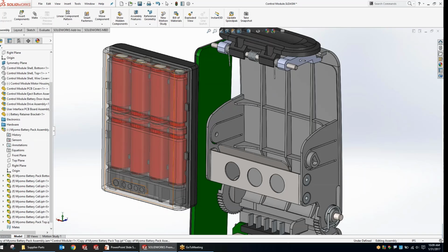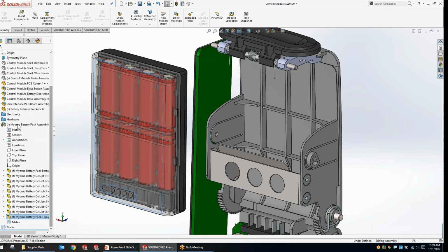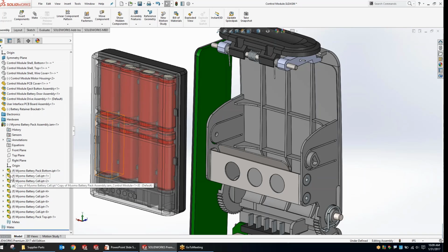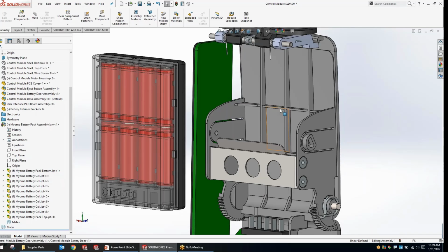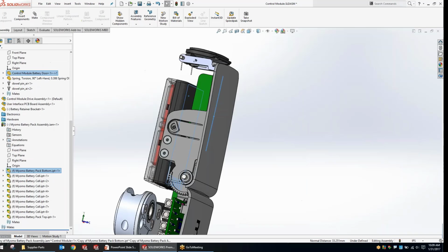So this assembly, once we've pulled it into our SolidWorks assembly, we notice that it has a typical assembly file structure. We can see each of the parts that are contained in that. And the beauty here is we see from these extensions and the 3D Interconnect icon is that these parts and this assembly are pointing back to those original Inventor files. So they're not just bodies in the assembly, they are pointing to those original Inventor files. And we can use them just like we would any other SolidWorks parts to locate them into the assembly.